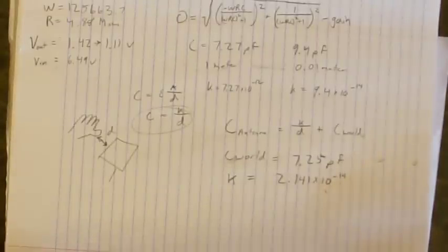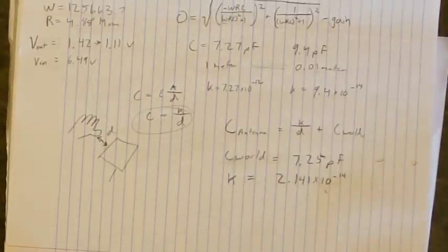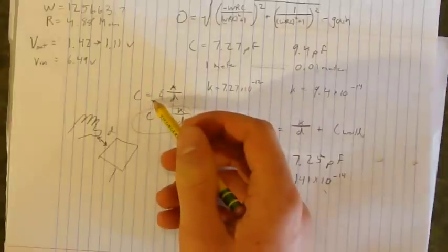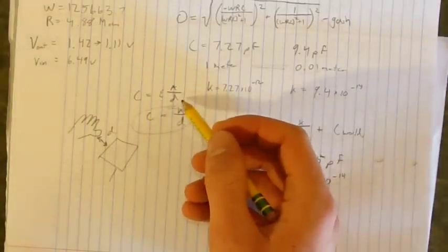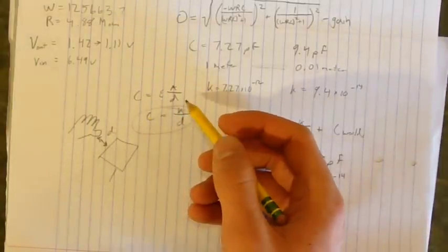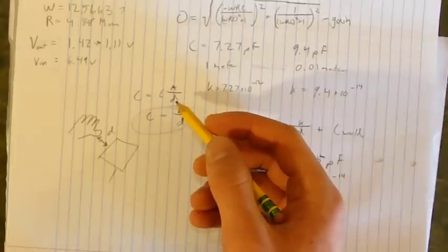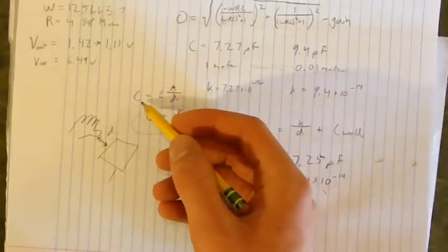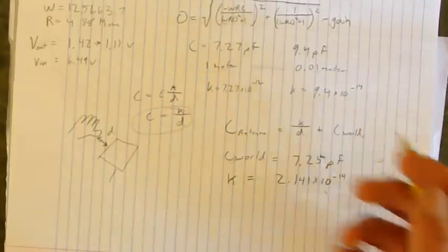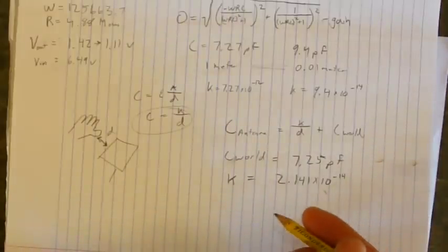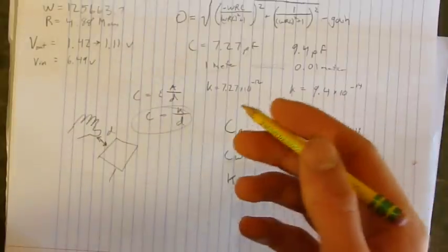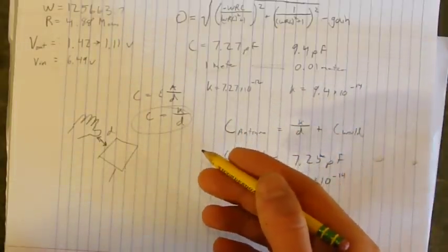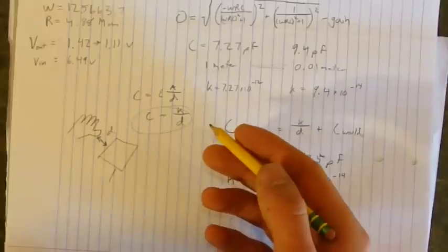Now we'll use these values when we're trying to linearize the output sound, which is very important for a theremin, because as you can see, the capacitance is not directly related to the distance, so that's not linear. Then we'll find that the frequency of our oscillator is not directly related to the capacitance, so that is also not linear. And then we'll find that the octave we're in when we're trying to create a certain sound is not directly related to the frequency.